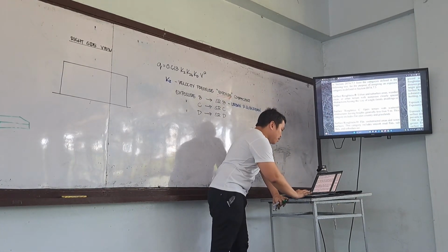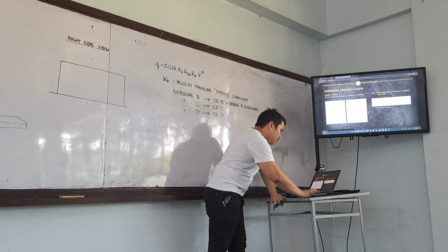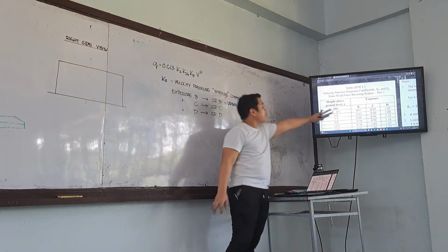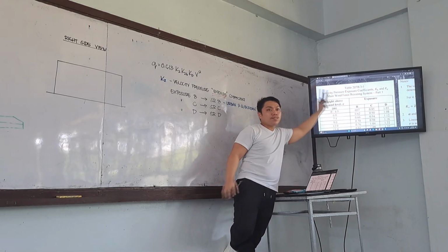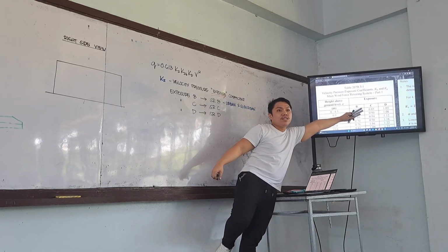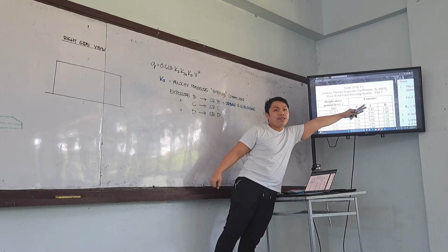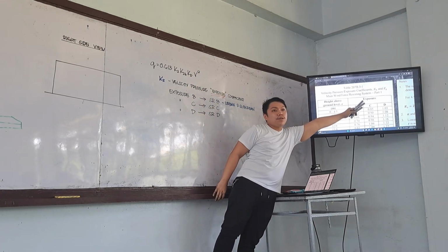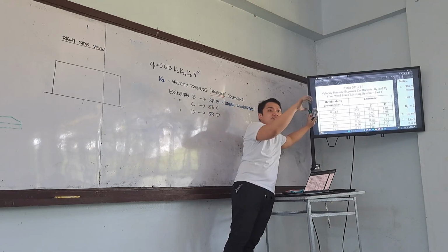Let's check our NSCP if this is right. Try to observe our surface exposures. From height 0 to 4.5, what is surface roughness B? It is the exposure wherein there are many urban areas and buildings. The reduction factor is large, reducing by 43%. But if it is open, instead of 1, your basic wind speed is magnified by 3%. Because it is open, when the wind blows there are no other obstructions to resist it before it reaches the building.